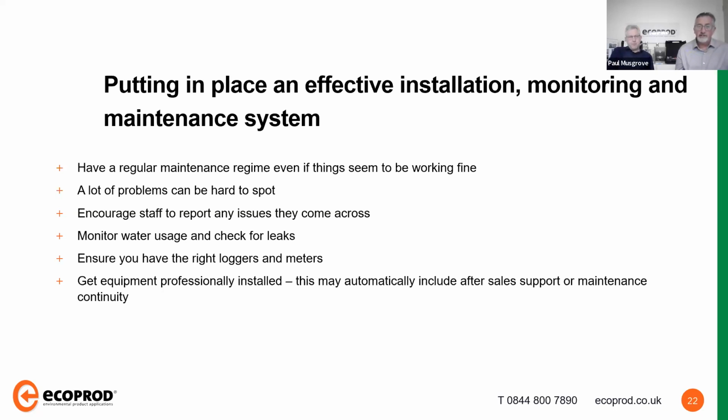So if we suggest and recommend to any of our clients a process of changing a product, installing a water management system, it's important that we encourage them to learn the products, simple training procedures. How often should you look after something? How often should you flush something? How often should you download reports? Looking for leaks, measuring all this. You need a PPM plan in place. Now, many good businesses do that, but then they don't necessarily have the qualified staff to enforce that.